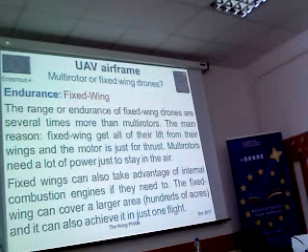For the endurance, the fixed wing will have a plus point, because the range or the endurance of the fixed wing is several times more than multi-rotors. The main reason is that the fixed wing gets its lift from the wings, and the motor is just for the thrust.